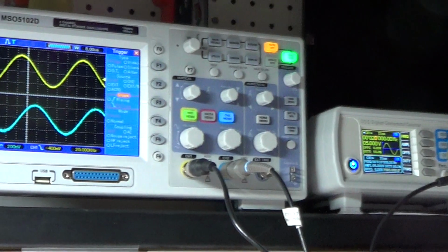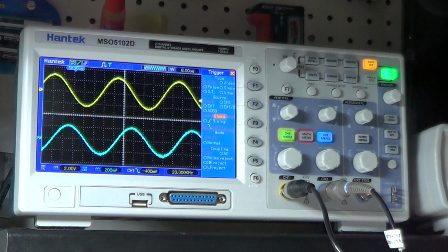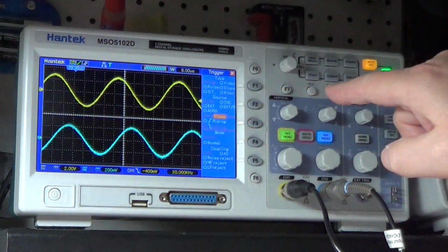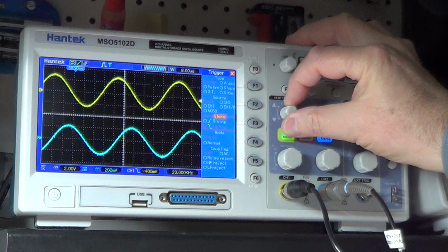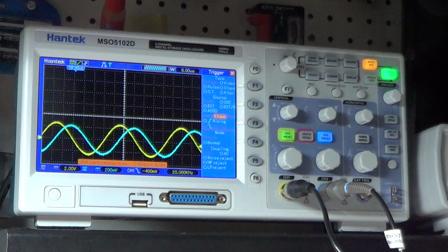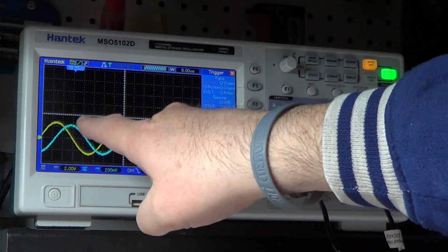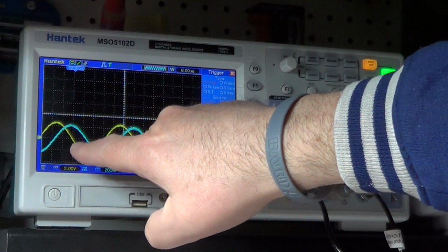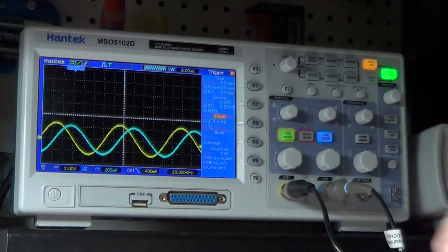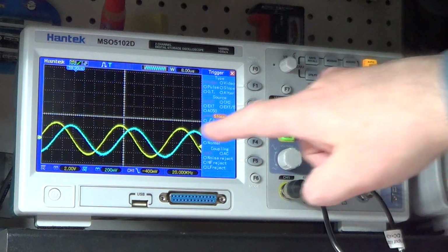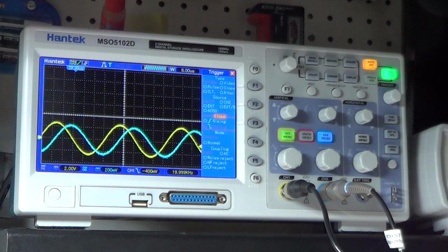So let's see what the oscilloscope shows us now. Here it is. You can see how the voltage in yellow and the current in blue do not change at the same time. Let me superimpose the two pictures so you can see better what's going on. There we go. You can see that when there is a peak in the current the voltage is zero, and vice versa, when there is a peak in the voltage the current is zero. This means that the two peaks are distant exactly 90 degrees, which is the time between the zero value and the peak of the input voltage. And because the current comes after the voltage, we say that it lags behind.